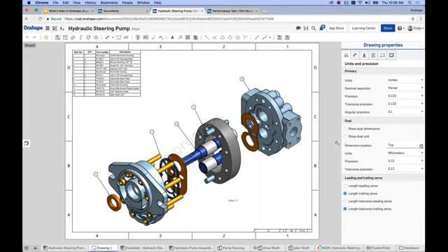So if you click the wrench, it brings out the flyout. You have a lot of the things that we could do, things like changing the units of your drawing, right? Changing the decimal separator or the precision of the individual dimensions. Dual dimension options, things like leading and trailing zeros. Those are options that we've had in the past. What I want to point out, though, is that in the drawing properties flyout that flies out on the right, you have tabs across the top. And this is how you access the various pieces, the various properties within your drawing.